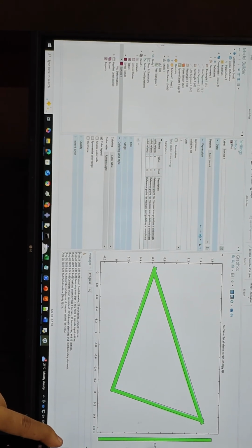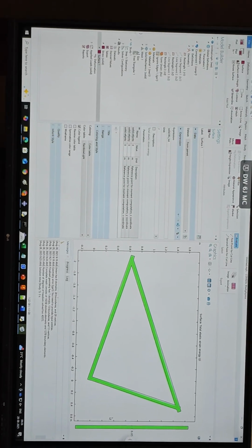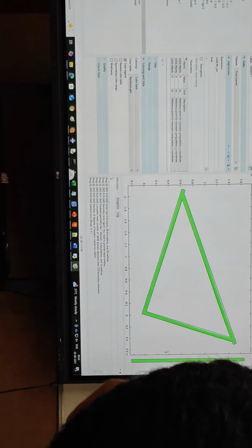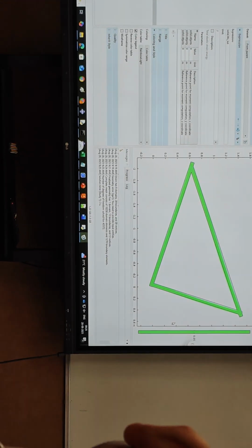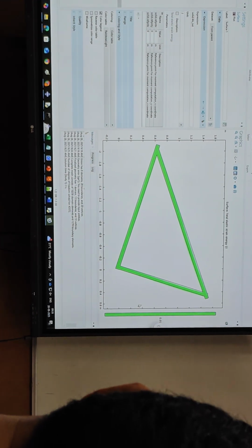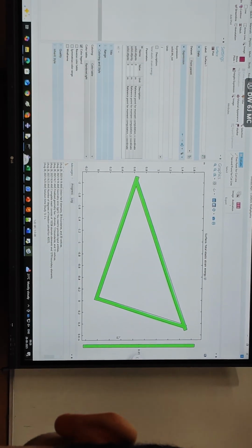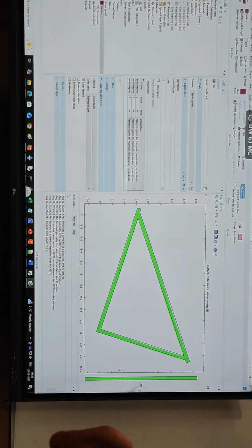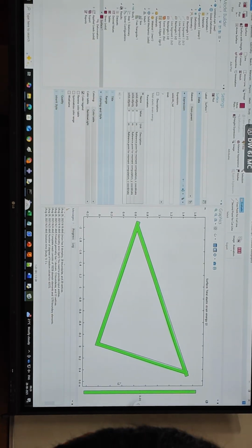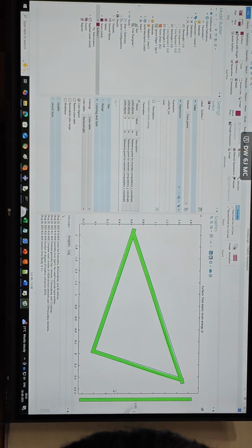So here, in this case, of all the values I've taken, it's 0.05, right? Now what is interesting to try is, this is in a way not considering the element as a truss. So it's also including bending. For bending, we know that cross section matters, right? If I change the cross section, I changes, and the stiffness of the structure will automatically change, because if I changes, bending is obviously restricted, right? So for that, you can also try taking the square root of your area of cross section,